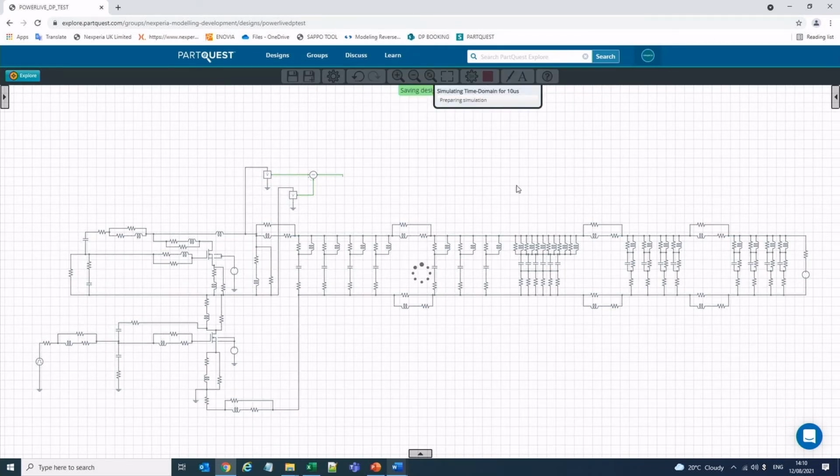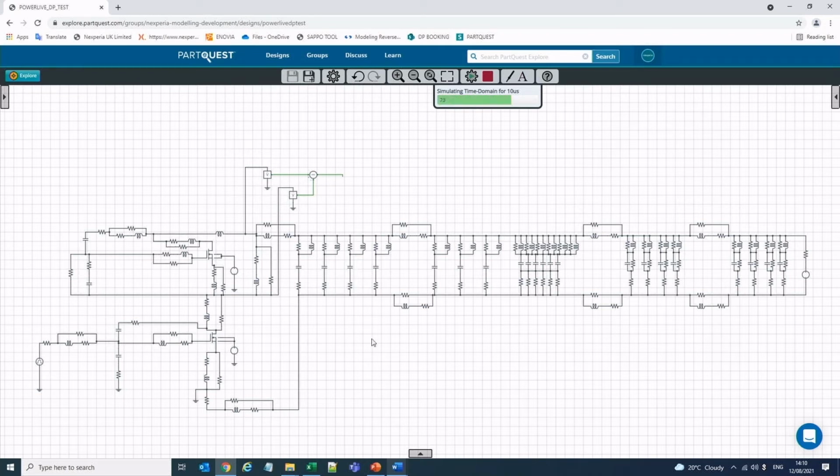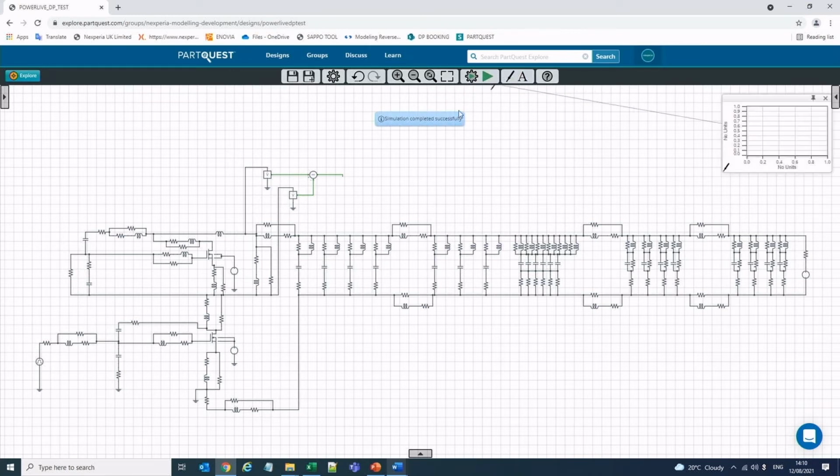and probe the signals that we just looked at in the measurements. Therefore, it will be the high side VDS of this MOSFET and the current through the MOSFET. So we can probe here the high side VDS.